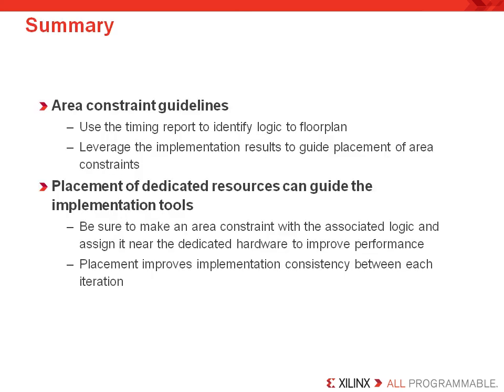In summary, to create an area constraint, use the timing report to identify logic to floorplan. Leverage the implementation results to guide placement of area constraints. Placement of dedicated resources can guide the implementation tools. Be sure to make an area constraint with the associated logic and assign it near the dedicated hardware to improve performance. Placement improves implementation consistency between each iteration.